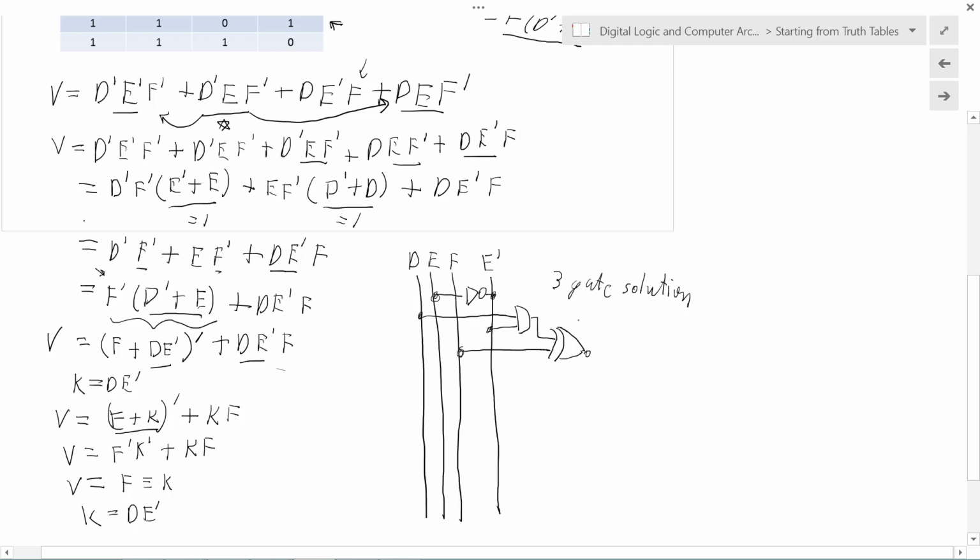Now, what is interesting here is that we went through many different steps of simplification using Boolean algebra. Using idempotency, we had to make the Boolean equation more complicated, which would have led to an even larger circuit to achieve this level of simplification. Recall from another lecture, if you have had the chance to view it, that logic minimization for multi-level logic, which is applied here, is very hard. Two-level logic minimization is NP-complete, and multi-level logic minimization is even harder. So it can be very difficult, but what is nice is that we can come to near optimal solutions by using a minimal amount of work.